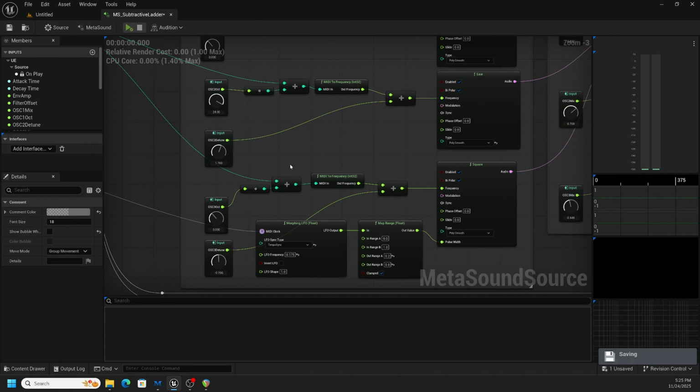Having the waveforms perfectly in tune is less interesting than having them slightly out of tune. I think of this as maybe a row of string players in an orchestra, right? We have several instruments playing the same melody, and the fact that no one's ever going to play exactly the same pitch creates an interesting and rich modulation, slight intermodulation between the voices. So by detuning our oscillator slightly, that adds a significant amount of interest to the voice.